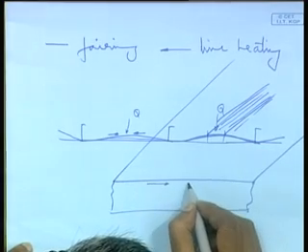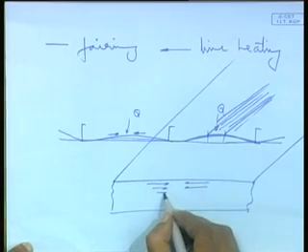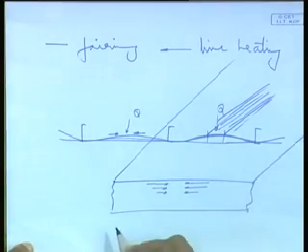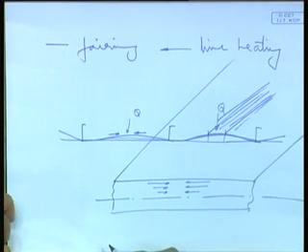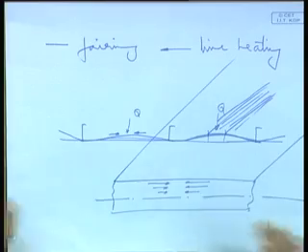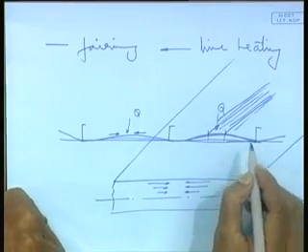and it's creating shrinkage forces again in the same way, not uniform but maximum at the top and gradually less. So it shrinks the upper part and gives a bending moment. It shrinks the upper part more. The bending it cannot do, but shrinks. So I will apply in such a fashion that it remains above the neutral axis more, controlled heating. So it tries to shrink, so it comes down, means it flattens up. That is what is line heating.